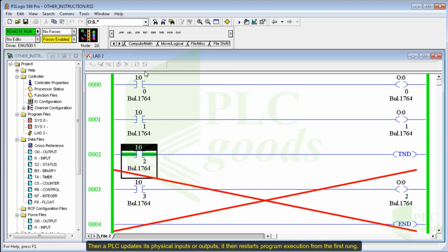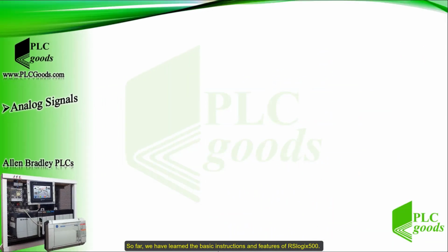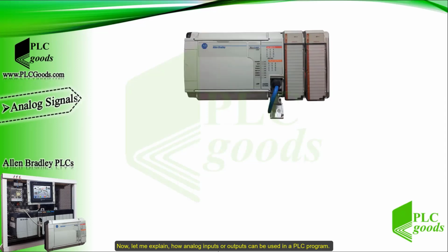Then a PLC updates its physical inputs or outputs. It then restarts program execution from the first rung. So far, we have learned the basic instructions and features of RSLogix 500. Now let me explain how analog inputs or outputs can be used in a PLC program.